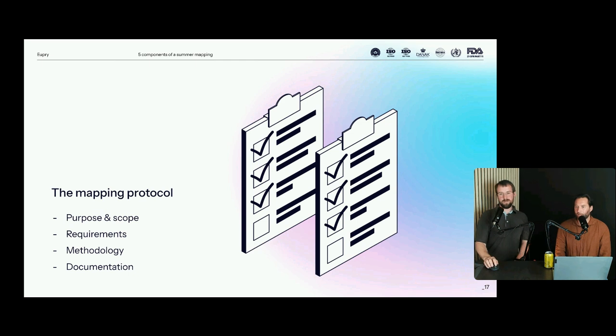And Mickey, you're also spot on. Usually smaller units require a higher frequency of logging, especially if you do door openings. I think it's more of a technical question, but again, today, if you can get 1-minute intervals for smaller units, just do it. The lower you go, the better. Yeah, the better.